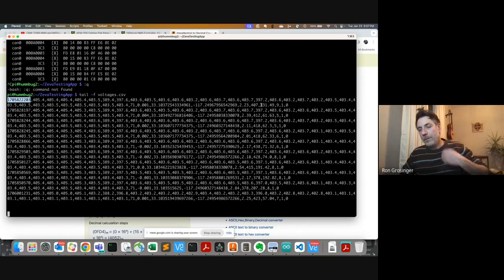Got it. Pretty cool. There's also some other stuff that's, I guess, possible. For instance, sometimes when I charge at a particular house, they have a small breaker, let's say a 20 amp breaker, which is surprising. Usually you have a 30 amp breaker at least on a 220 line, and it was a 20 amp breaker on a 220 line.